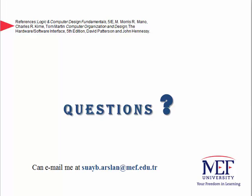So in this class, we covered a single-cycle computer microarchitecture. We talked about basic building blocks of a load-store model, register file, and a functional unit. In general, we start with ISA and computer specifications before we attach the implementation problem to the general picture. The ISA is presented in this session after the microarchitecture, but in reality, the order is usually reversed. According to the ISA specification, we have seen a design of the functional unit and introduced the hardwired control, and in the next class, as I said, we will focus on multi-cycle computers and two control approaches to both single and multi-cycle computers.